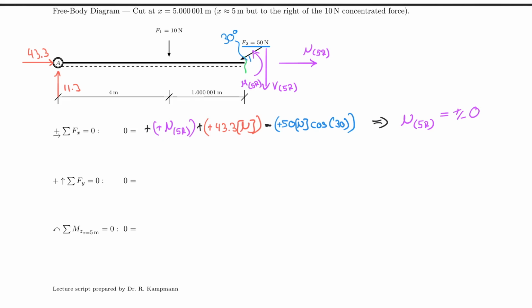And that is a result, believe it or not. So you cannot get away with just leaving it out. You have to calculate it, and you have to mathematically prove it, and you have to double underline it. But the explanation here is that this is really the x component or parallel component. And that parallel component balances the 43.3. And that makes perfect sense, hopefully.